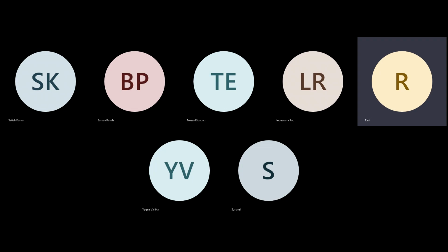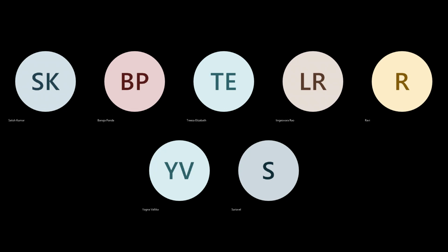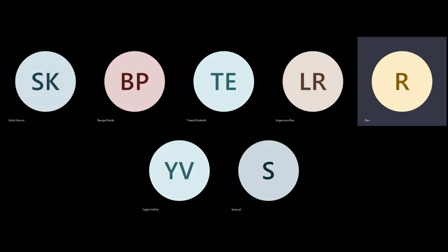Basically, it is trying to use your cells as they are, where it is doing coarse placement. In coarse placement, it is not optimizing, it is not sizing, it is not doing anything else. It is trying to place the cells as they are, but within the context of route length. Now, if you are doing timing driven placement, then it will start analyzing that as a criteria first. Okay, first for the generic case, I will tell you. So route net length, that is what it is placing.